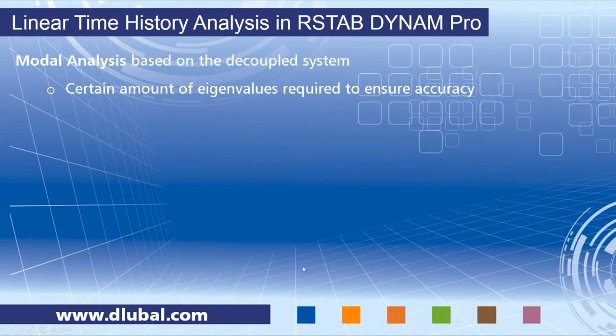So the modal analysis, now I concentrate really on RSTAB, DYNAM Pro today. The modal analysis in RSTAB is based on a decoupled system. So you really need a certain amount of eigenvalues. This is required to ensure the accuracy. And how can you know whether or not you have enough eigenvalues? You can have a look at the effective modal mass factors. And it's also important to compare natural frequencies of your structure and the excitation frequency that you have.